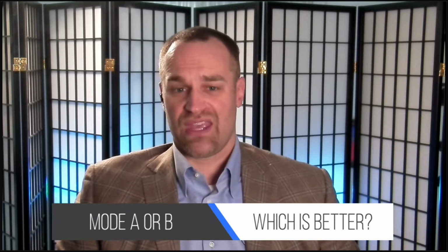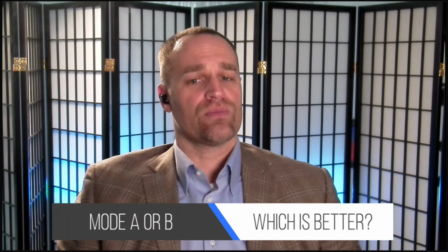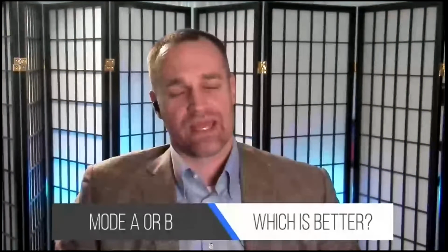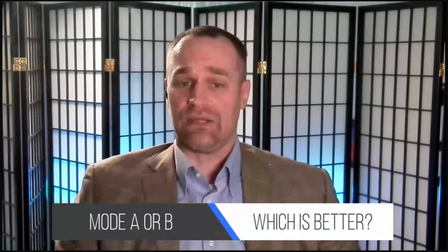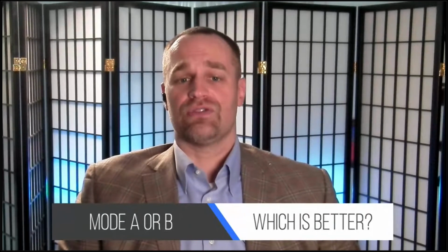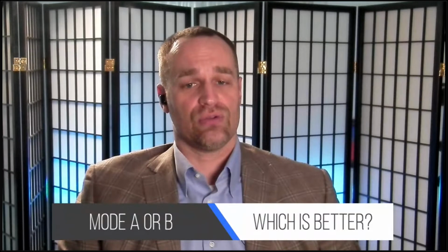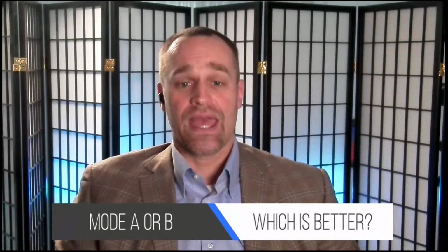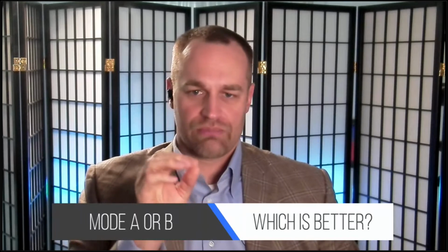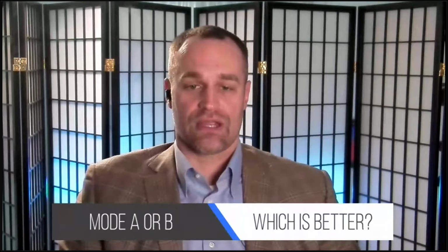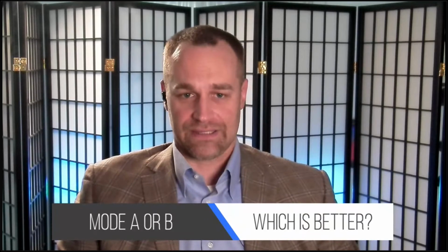And again, is one better than the other? No, both mode A and mode B perform just as well as long as they have the right mode for the job. And mode AB, where you have power in both pairs, gives you the full 16 to 90 watt power, or IEEE 802.3bt PoE. I covered all of the IEEE 802.3bt and 4-pair PoE in our previous webinar here in Realcomm, so I do recommend going back and checking out the YouTube channel where I covered it specifically.